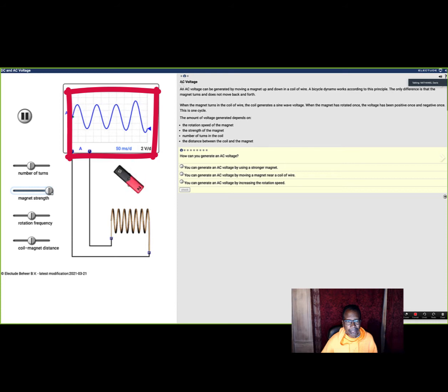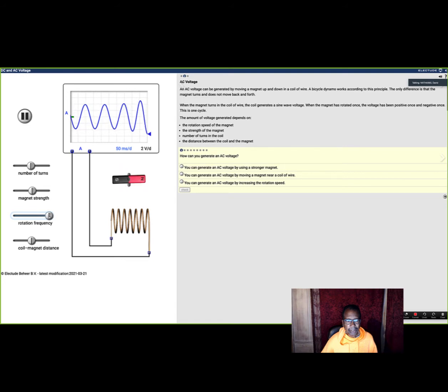Look how wide it gets. Now a low strength or weak magnet. Look how small it gets. When the speed increases, the signal gets bigger. I have seen cars that when you increase the RPM, the car will run, but at a lower RPM the signal got so weak the car wouldn't run.